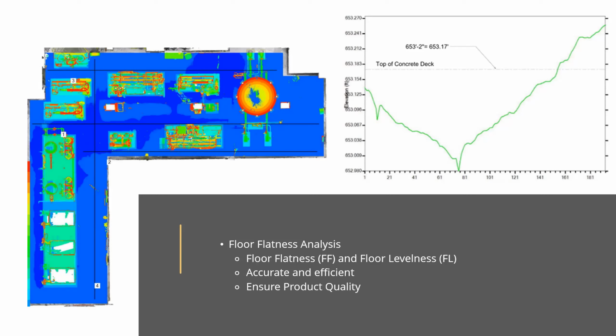In other words, the thickness of all the new pads can be different, but they must come to the same top elevation. With the analysis, the superintendent doesn't need to go to the site and do the survey at 7 different locations. Instead, he was able to pull the information from the report and quickly identify the highest point as the benchmark point for all the pads.